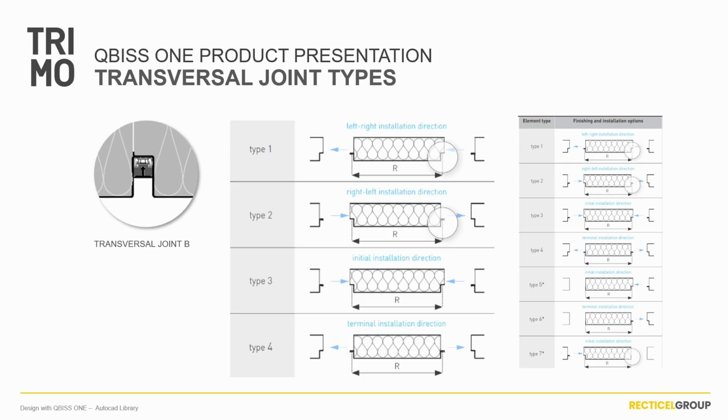On the other side, transversal joint is formed at the edges of the facade elements, where the panels are fixed directly to the supporting structure using washers and screws. Dimensions of the joint are 25 per 24, and to ensure a complete air and watertight seal, the joint is finished with an inserted sealing gasket and a decorative aluminum profile.